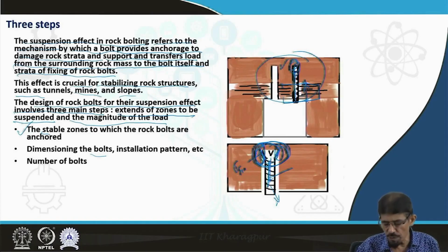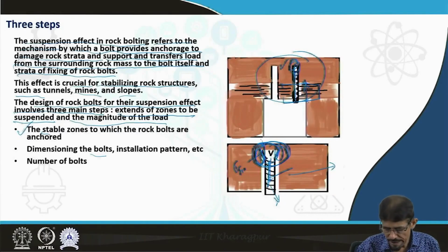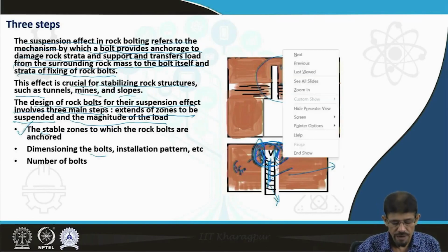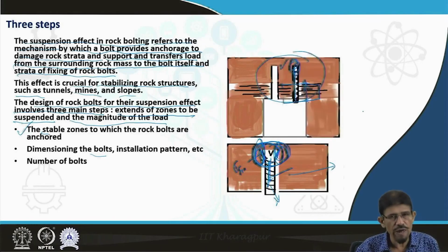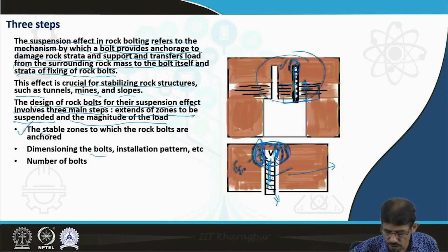Therefore, we prefer grout anchored rock bolt, because in future this type of bolt is going to show creep problems in metals and loosening in contact between the walls of the hole and the surface of the bolt, etc. In case of the grout anchored rock bolt, we insert the grout inside this and we have three interfaces.